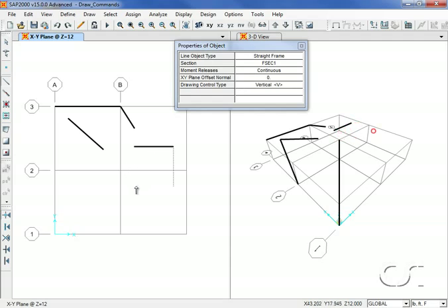Similar controls are available if we hit the V key or A. Note that the angle is 45 degrees. And L, which draws a fixed length object. Clicking the Set Select Mode button exits the draw mode.